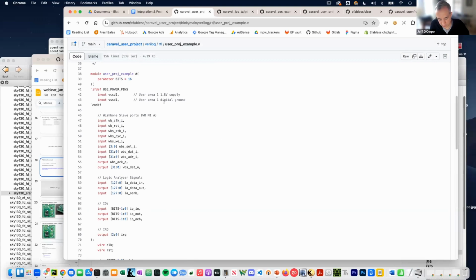Also, it's important that you have the macro hooks included as well. You can go all the way through PNR, and the design will look like it passed successfully, but you don't have power connectivity. Even with a full LVS, you won't catch it if you don't have power connected correctly in your Verilog.